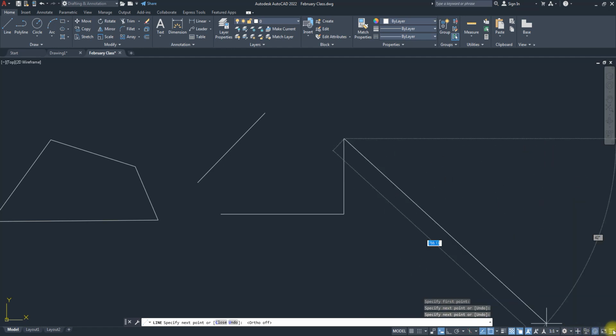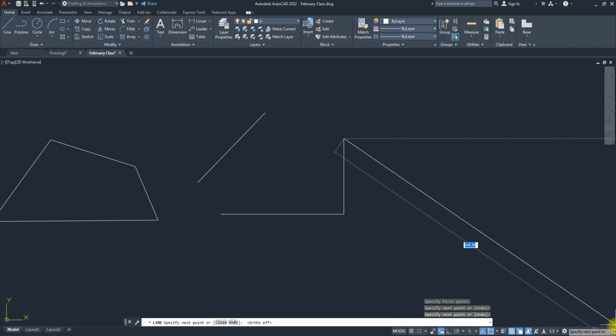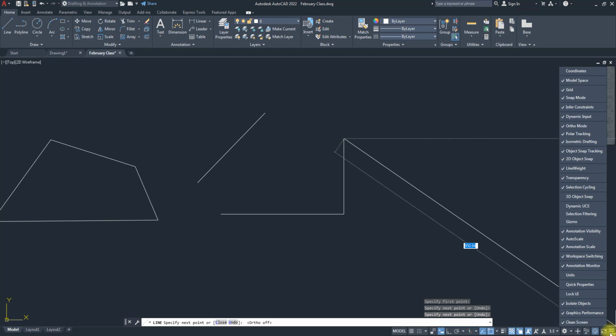If you come to this customization icon by the side here, you have three horizontal lines. That's the customization icon. If you click on it, you are going to see all the things that you want to be represented down there. So you want to look for dynamic input. Please, I need us to look up. Make sure it's checked. Once you have it checked, it's going to bring it down there. I know it's down here, but in your own case, you might not have it. So look for that dynamic input and check it.